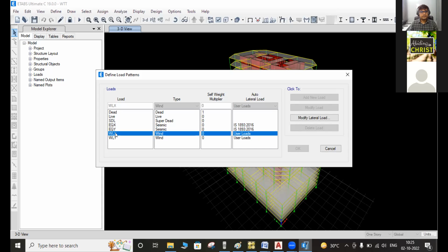It is a long procedure to calculate manually or apply the point loads along the x direction, y direction, and the moment. So the force coefficient or gust factor methods are both considered. The Indian standards have the formula available, but it is a long procedure to calculate and apply. Using the American code, a different formula is also available. You can calculate manually also, or use a wind tunnel to calculate the point loads from wind.